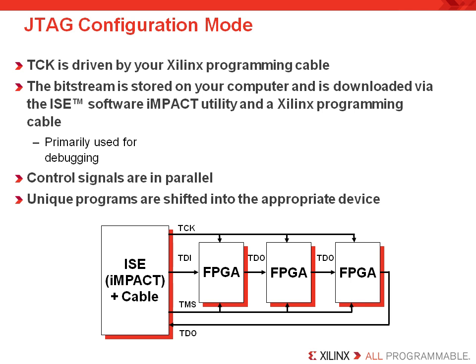While Xilinx does not specify configuration times, downloading with JTAG takes between a few seconds and a couple of minutes. This is done at default cable speed with the Platform Cable USB being used. Now this will vary depending on your PC, FPGA, and, as I mentioned, the programming cable you choose.